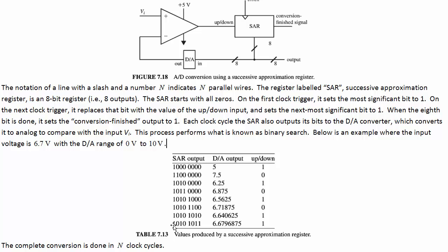So all in all, I think I said, I'm not sure if I said 256 was just the 4. No, that's wrong. It's 16 is the 4, so 256 is the 8. So all in all, we get 256 different binary numbers representing split between 0 and 10. That means 128, this number here in binary, corresponds to 5 volts, and 11000000 corresponds to 7.5, etc.